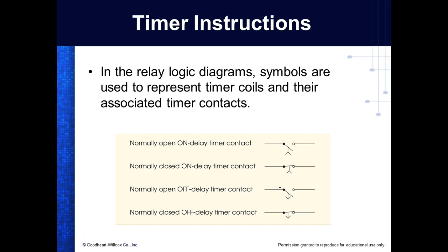So on the input and the output side, you are in electrical controls, right? Inside the PLC, you're using either examine if open, examine if closed, or these other things that are available to us. So, y'all understand? So this is a normally open, timed closed. This is a normally closed, timed open. This is a normally open, timed open. This is a normally closed, timed closed. Did you hear the way I said that?